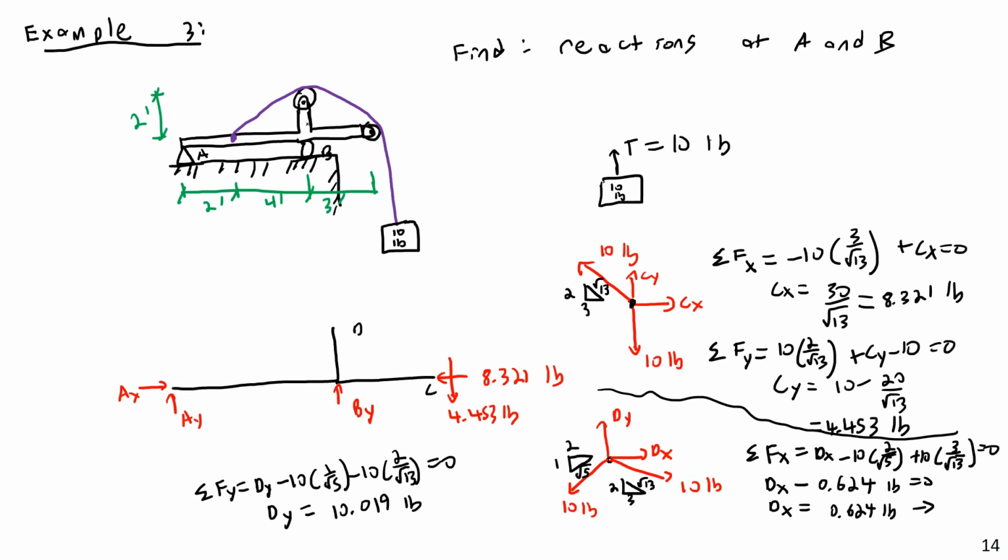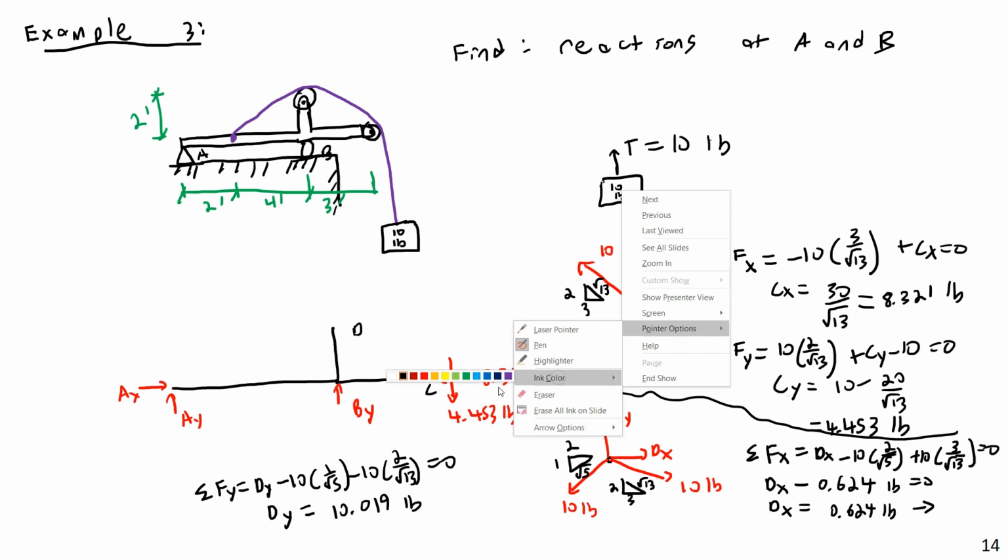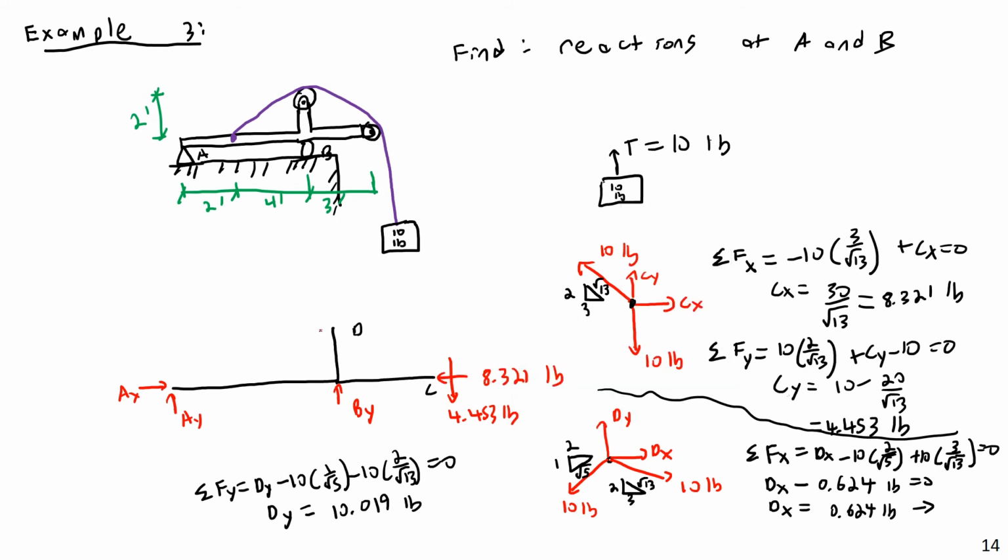Then I want to apply those forces to this diagram, and I'm going to apply them in their opposite directions. So now the dx will go to the left, again, equal and opposite forces. I calculated the forces that are holding the rope in place, but that's the forces being exerted on the rope by the pulley. What I need to draw here is the opposite.